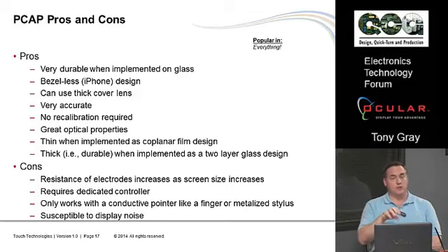The thing is, if you do that, you lose some of the benefits of having dedicated silicon to do all the complicated analog measurements, because you're trying to measure capacitances that are in the 5 to 10 picofarad kind of range, and so it's very, very difficult to measure those values with off-the-shelf microcontrollers without using really long scan times and high count A to Ds. And that's one of the reasons, as I mentioned before, that it also tends to be more expensive, because you got to buy the touch panel as well as a controller to go with it.